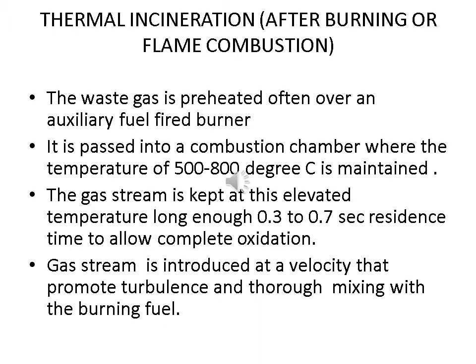Thermal incineration. The waste gas is preheated with the help of a fuel-fired burner, and it is passed into a combustion chamber, where a temperature of 500 to 800 degrees Celsius is maintained. Then the gas stream is kept at this elevated temperature long enough to allow complete oxidation.